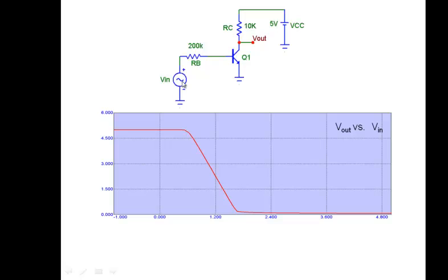So I took my VBB out. Before I apply a signal, when Vin equals 0, where am I operating? Where is my transistor? Say Vin is 0, that's the signal that you want to amplify. Do you all see that it is at this point? Because if Vin equals 0, this is where I am. My operating point is here.